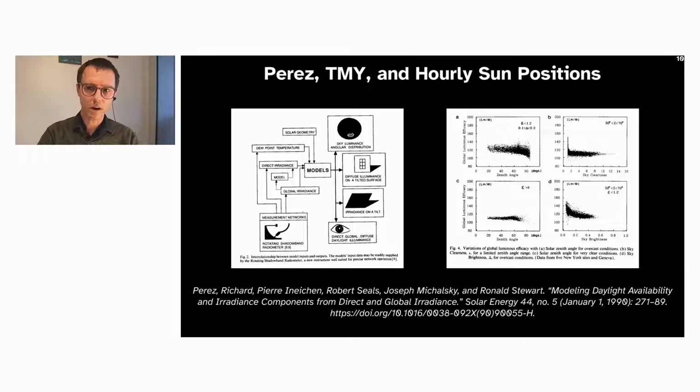Regarding the model, the commonly used Perez all-weather sky model is often taken as an instantaneous distribution, which in the case of the sun location, it is. But the brightness of a particular sky region is really a prediction of the average condition for all skies with the same input parameters: sun position, direct normal irradiance, diffuse horizontal irradiance, and the dew point temperature.